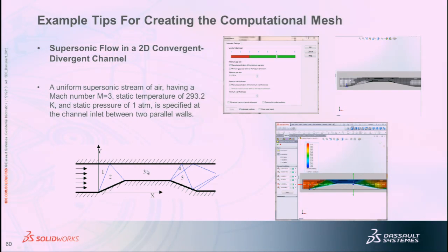Okay, here is another. This is actually a supersonic flow problem, 2D converging, and from literature we know exactly where the shock waves occur off of each of these, and you can see in the model that they are captured. You can also look at the solution adaptive mesh that was turned on at result resolution 6, and you can almost see where the shock waves are in relationship to the mesh, and you can definitely see the high gradients. This is Mach number that we're seeing. This was Mach 3, actually, at the inlet.